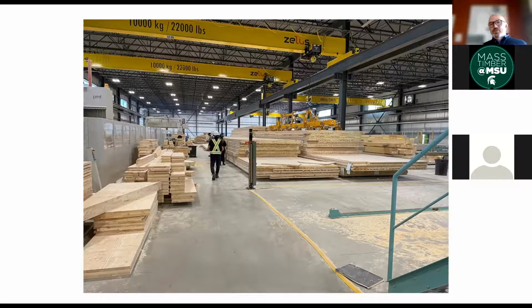And if there's any penetrations that are necessary to install ductwork and those kinds of things in the CLT panels, ideally we want to draw those in the BIM model and pre-cut those in the factory to facilitate the installation of the mechanical system. So every panel is numbered and has a unique location where it fits within the structure. Beyond that, they all get covered and they go onto a flatbed truck and they are shipped to site where they are assembled, much like IKEA furniture. Next slide, please.